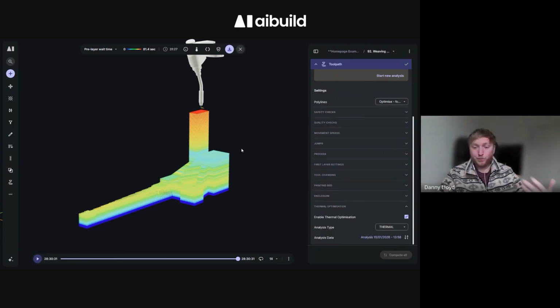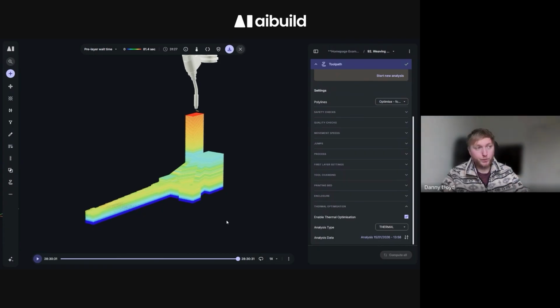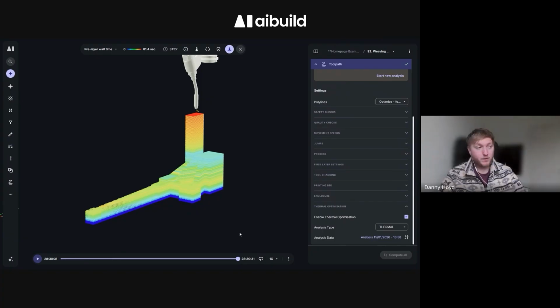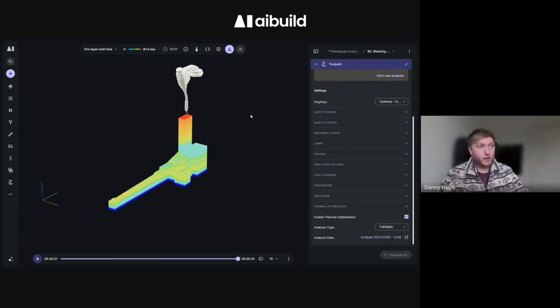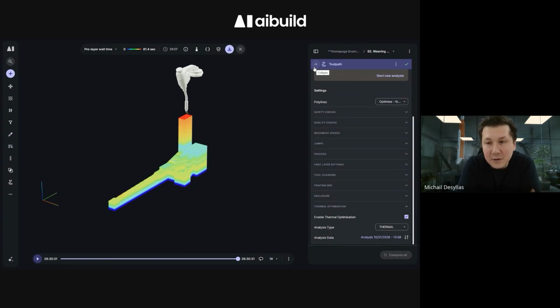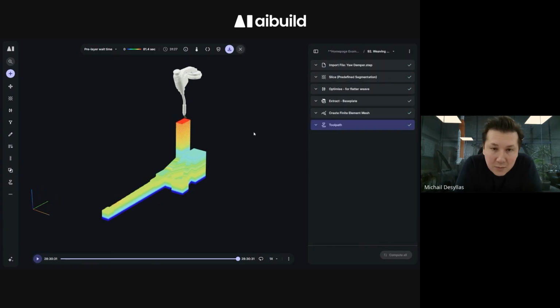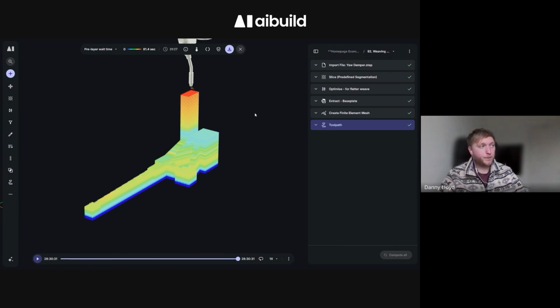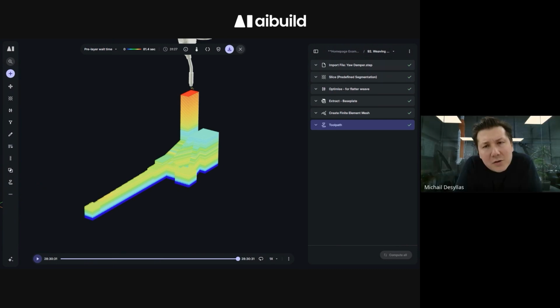You get accurate production time estimations as well, because the printing without the pausing, just straight printing, is about 15 hours. When you add the pauses in between the layers, we've nearly doubled the print time. So that's important for production planning and time estimation. So that's also had some general improvements. We'd have to make it by hand without the analysis. Yeah, exactly.